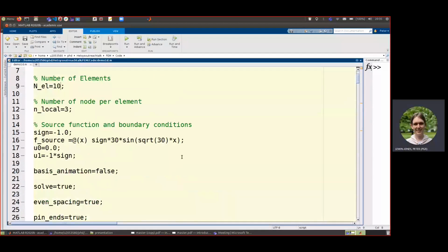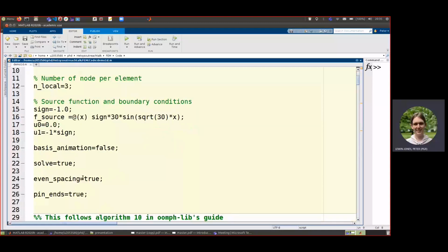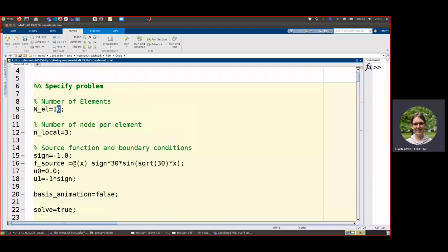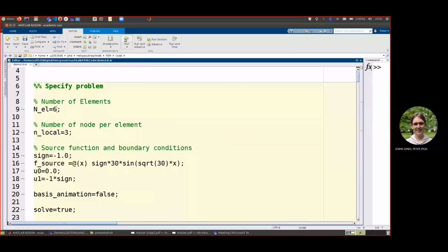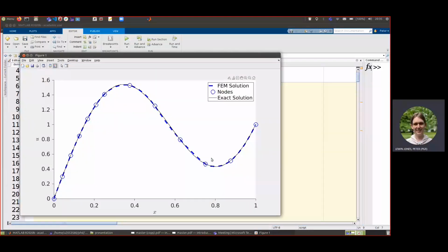The last thing to mention is that there's no need for the elements to be the same size. I've also included something where I have split nodes between different parts of the domain. So here's an example where you can put more nodes at one part of the domain than another. I've spread them so that there are more elements in the left part of the domain as opposed to the right. I think I put the divide at about 0.25.